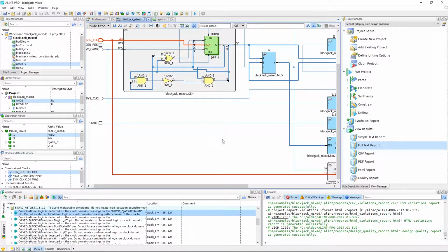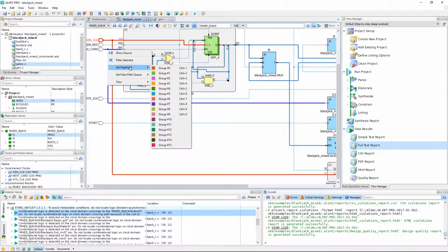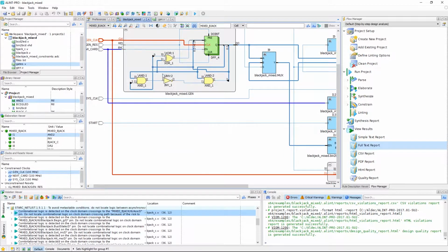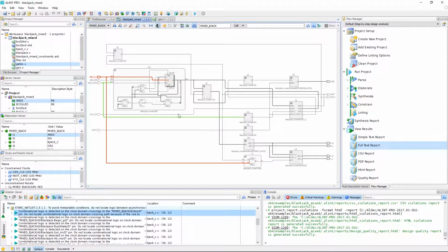When we do cross-probe, you may have noticed that the unit or signal in question gets highlighted a different color, and this is a result of the tool's highlighting options. Right-clicking on a part of your design provides the option of highlighting that particular part, and coupled with a gray mode here, we can set up the schematic to emphasize important parts that can be documented for a report, for example.